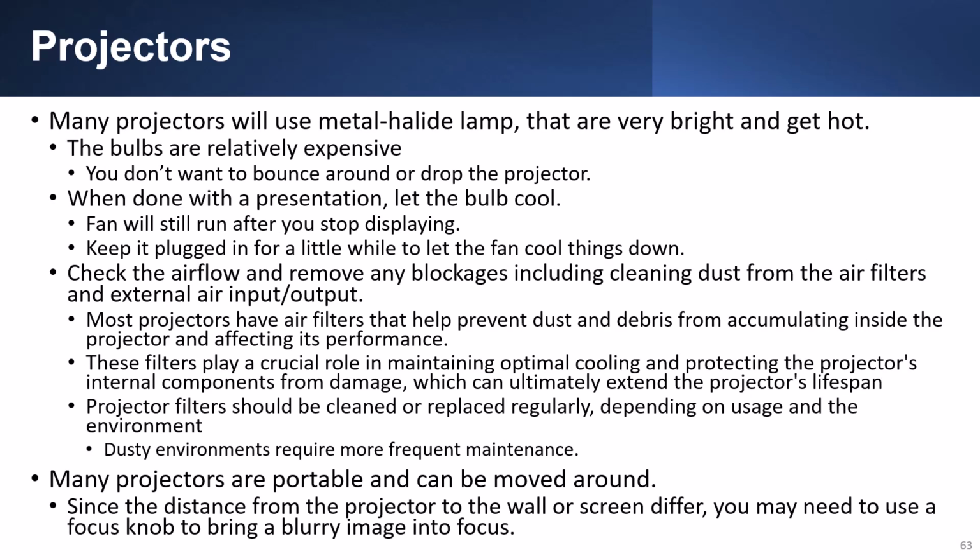Many projectors will use a metal halide lamp that is very bright and gets hot. The bulbs are relatively expensive. You don't want to bounce around or drop the projector. When done with the presentation, let the bulb cool. Fans will still run after you stop displaying. Keep it plugged in for a little while to let the fan cool things down. Check the airflow and remove any blockages, including cleaning dust from the air filters and external air input-output.